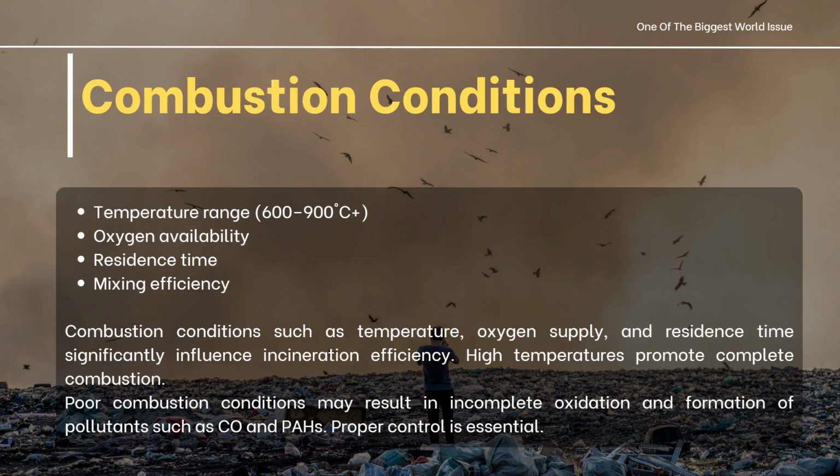Next is the combustion condition. The temperature range is around 600 until 900 degrees Celsius. The oxygen availability, residence time, and mixing efficiency. Combustion conditions such as temperature, oxygen supply, and residence time significantly influence the incineration efficiency. The high temperature promotes the complete combustion. The poor combustion condition may result in incomplete oxidation and formation of pollutants such as CO and PAH, so proper condition is essential.